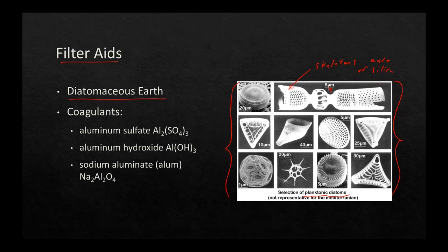So if you ever find yourself using diatomaceous earth, you got to know that this is not just mud. This stuff here is silica, and it's super, super fine. Obviously, you can see it's microscopic, and this stuff here causes silicosis, which is kind of like asbestosis. So it is dangerous, and you need to wear PPE. You need to wear respiratory equipment when you handle this stuff. And I know this because I handled this for 8 years when I worked at that swimming pool.